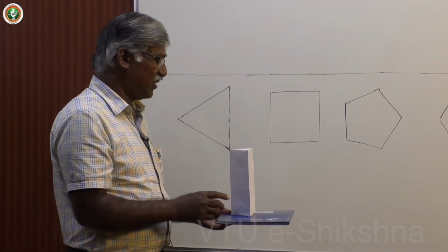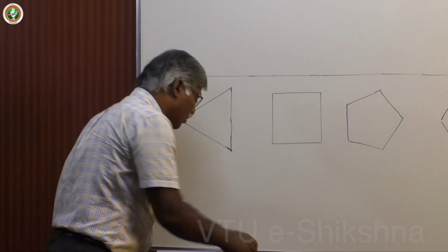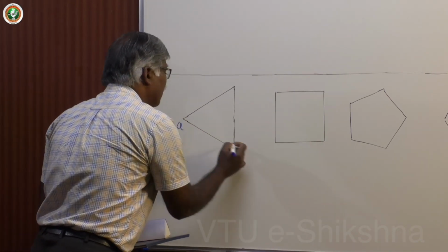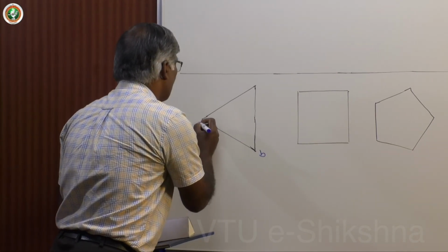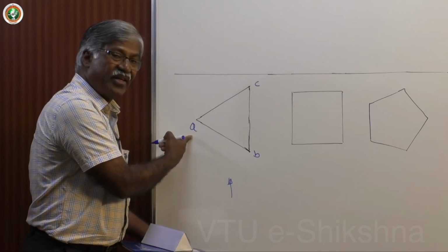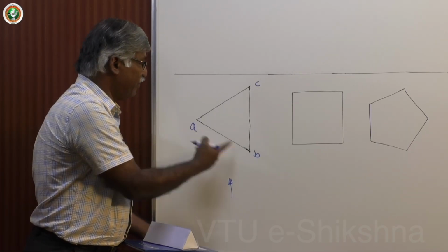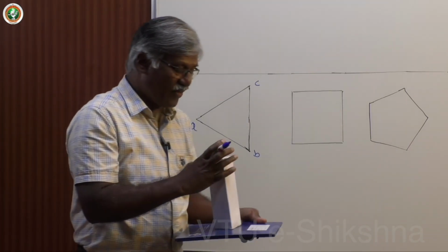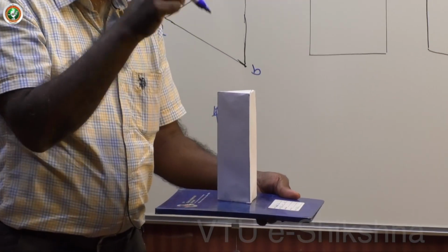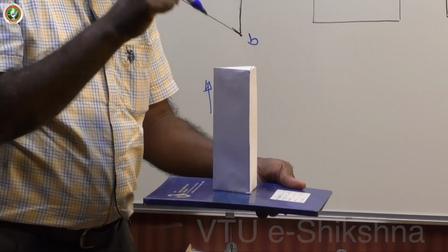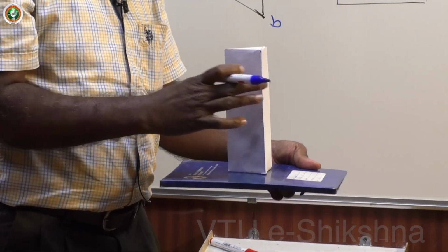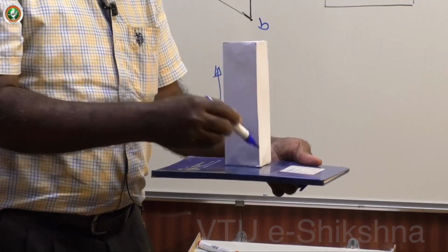Now let me start from this. What about the top view is this. Now where to start the top view? Naming should be done like this: A, this is B, this one is C. See, here I am, this is the left extreme nearest corner, you have to start from this: A, B, C. Okay, these are the top face corners. What about the base corners? If you look from the top, the base corners exactly coincide with the top face corners. As such, the base surface exactly coincides with the top surface. The base is not visible since it is on HP. Now this is A, B, C. This is A1, B1, C1.